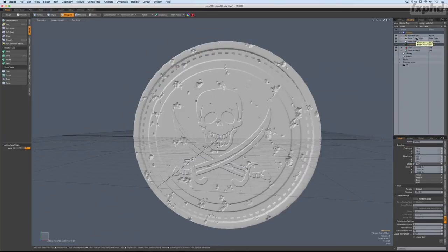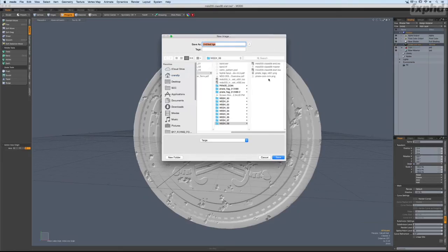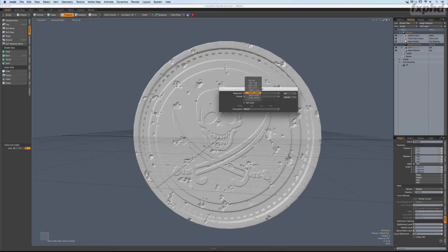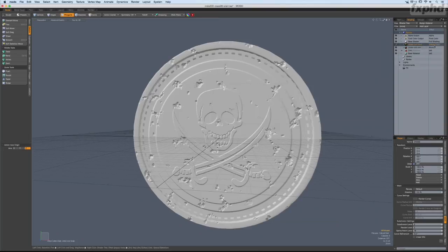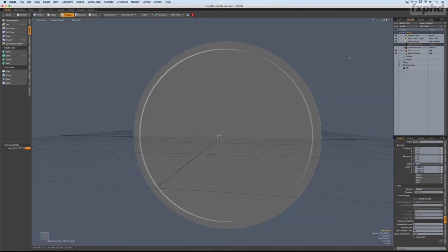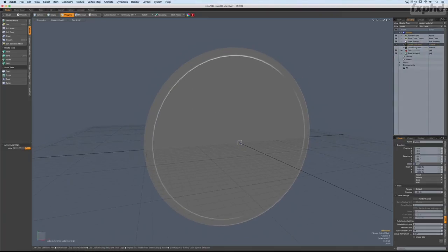I'm going to create a new normal map here, so a new image, just so we have a point of comparison. Let's create a new image. And I'll just call this Pirate Norm 2. Make it a PNG. Once again, it'll be 1024 RGBA. Things are good. And unlike last time, I'm going to remember to change the effect to normal before I start. There we go. And let's go ahead and bake this one out.